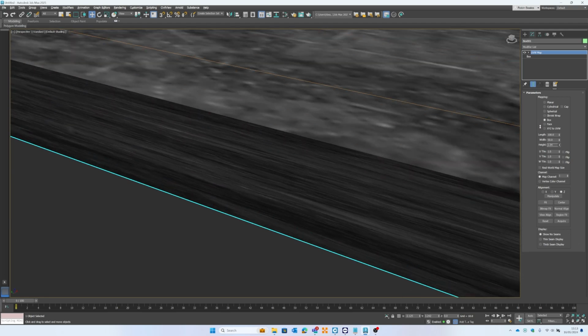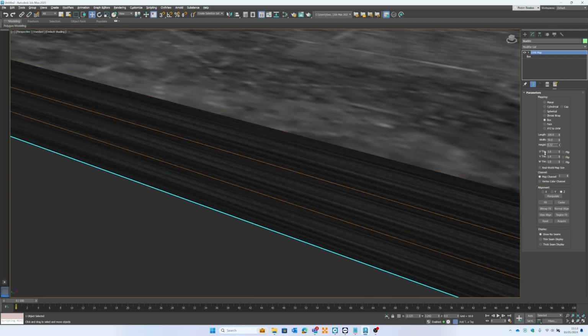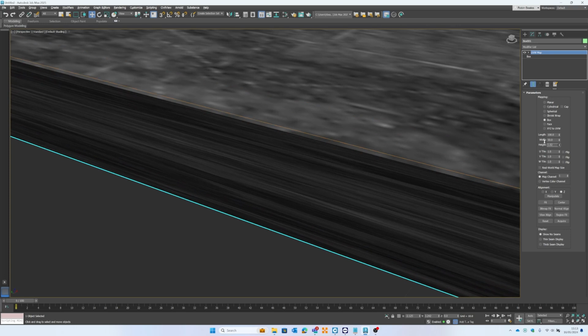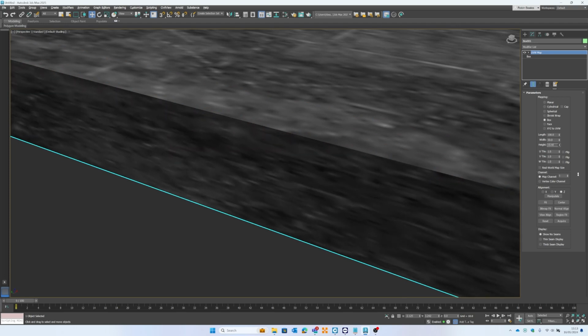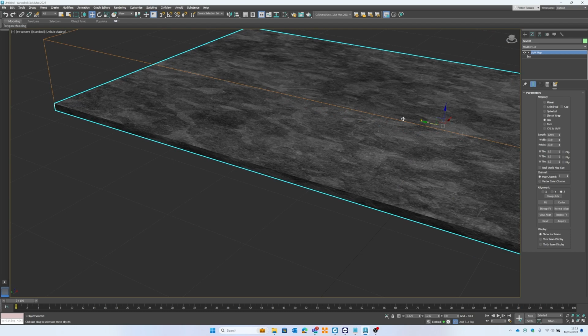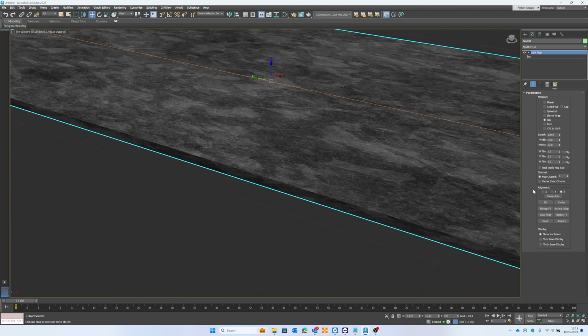Again, it's a massive texture. It's a 4K texture. It's huge. And we're trying to squash that whole 4K texture onto a 1mm thick piece of metal. So it just looks squashed. But we can play around with this if we want to by eye and start, saying that it looks about like that. The other thing that we can do is tell Max that actually the texture should always be displayed full size, and it gives you a better job of scaling. But we can control this pretty nicely and get something that works quite well.